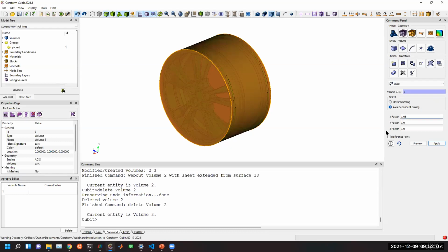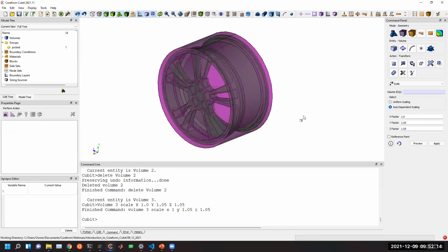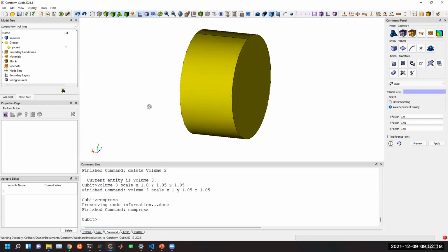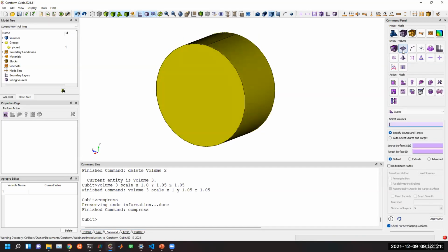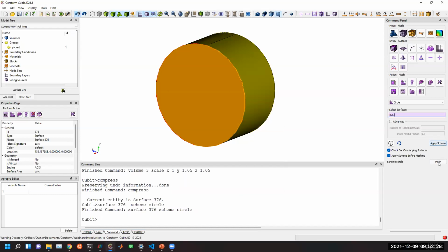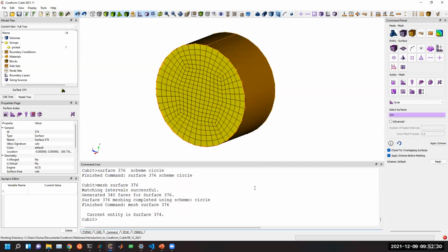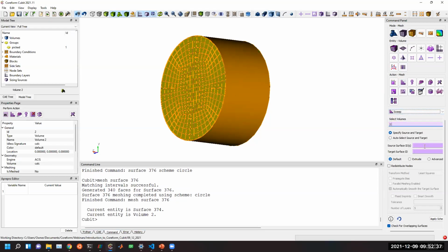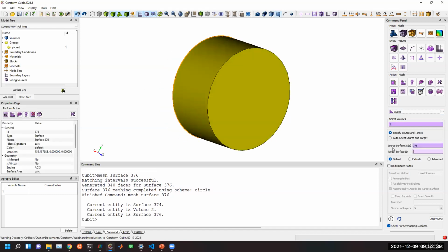numerical robustness issues that we're resolving, I'm just going to give a little bit of scaling here, maybe 5%. Greg, I'll just note there are some questions that have come in about the hex meshing limitations for using IGA, and this directly addresses those issues. Yep, exactly. And so now our mesh here, we can just do a simple mesh that's trivial to generate on this volume. And I'm just going to do a sweep now on this volume from front to back.